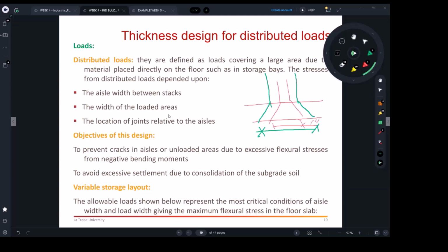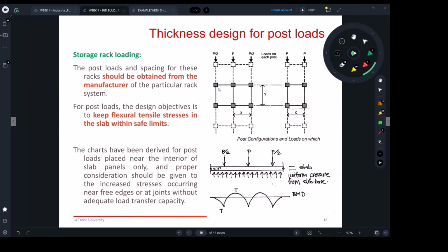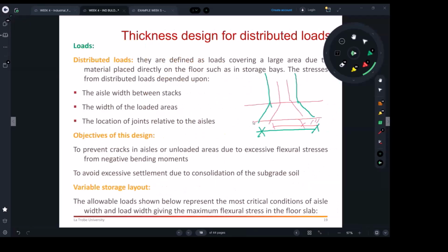Okay, so whenever the width of your legs, the width of the supporting posts, is bigger, it will reduce the stress on the soil. But if it goes skinnier, maybe you found a cheaper material, a better material, which looks skinny and may look better, remember, if it's smaller, it will cause more point load stress, and you have to double check if the soil is going to be happy to work with it.